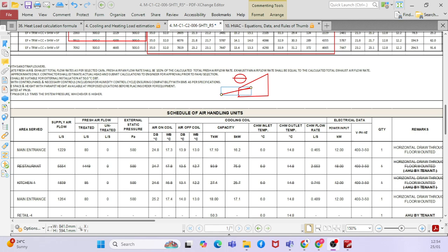When you try to enter the values in the app, now you have some knowledge. Whenever you calculate, why do you apply weather properties? Because you should calculate the delta T, the outside temperature and the inside temperature. That is why you require the outside temperature. You feed all the values in the app, and the app automatically calculates the heat dissipation for each and every component, then gives you the total. Clear, right? So you got the idea.